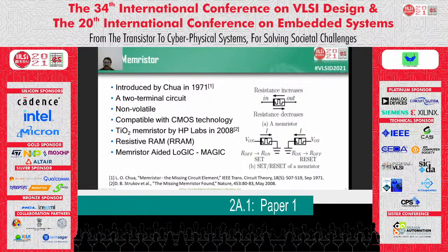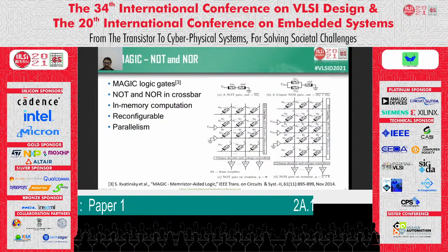The memristors can be used to design the resistive RAM, which is non-volatile, and also the memristor-aided logic circuits. The memristor-aided logic circuits, or the MAGIC logic circuits, can be designed to realize any logic operations. The NOT and NOR logic memristor-aided logic circuits can be installed within the memory crossbar, and this NOT